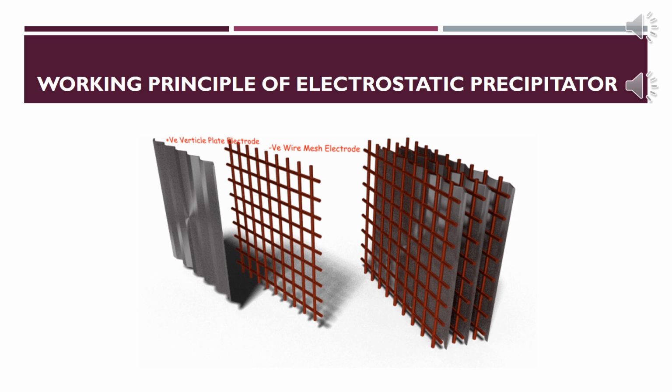The negative electrodes are connected to a negative terminal of high voltage DC source, and positive plates are connected to the positive terminal of the DC source. The positive terminal of the DC source may also be grounded to get stronger negativity in the negative electrodes. The distance between each negative electrode and positive plate and the DC voltage applied across them are so adjusted that the voltage gradient between each negative electrode and adjacent positive plate becomes quite high so that they can ionize the medium between them.